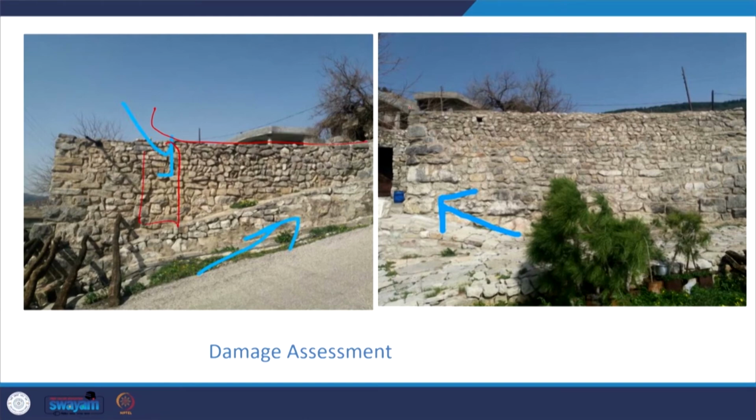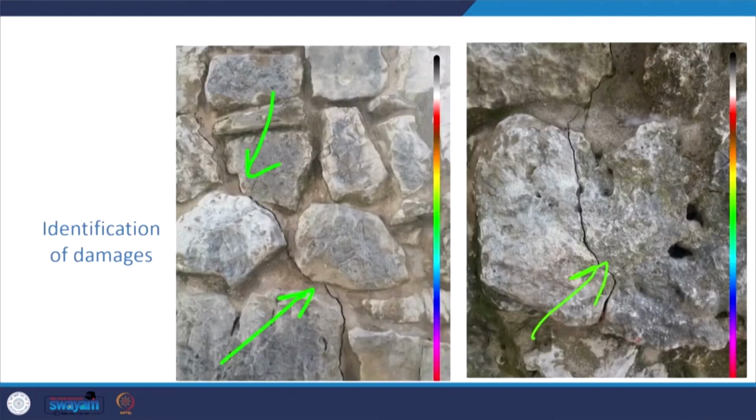But here we can see, whatever we have discussed, the corners of the quoins are actually composed of the larger stones, which give certain conformity and structural stability as well. Now, in the process of documentation of the damaged conditions, you can see that there are already certain plasters which were applied a decade ago.